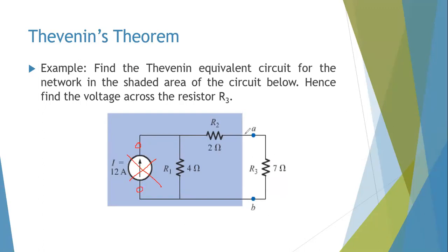Okay. Now, if this one is taken out right from the start, and you send a current here, the current simply flows here, flows here and comes back. No current can flow here. So this case is very simple. Your RTH is these two resistances in series, because the same current flows through these two resistors and comes back. Your RTH is simply equal to 6 ohms.